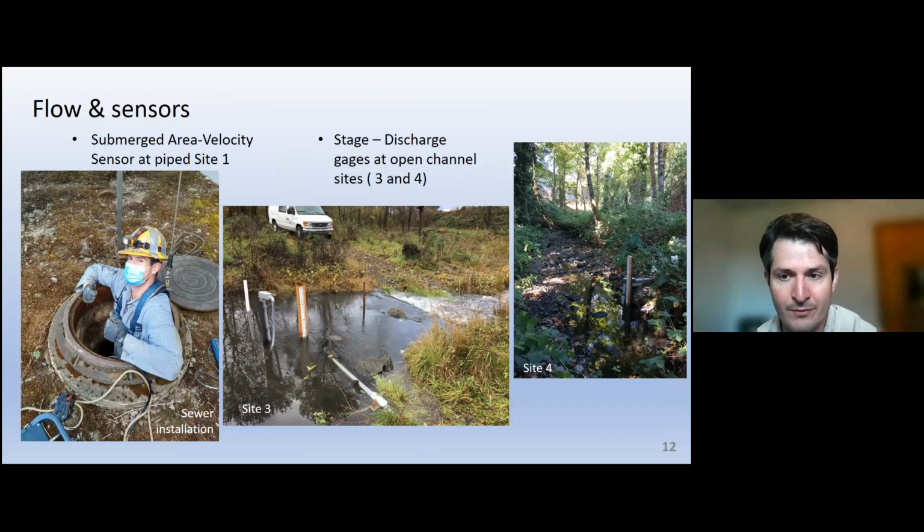And then at sites 3 and 4, we used a stage discharge flow measuring approach because it was just an open natural channel, which meant we needed to install these staff gauges and do some discharge measurements and create a rating curve.